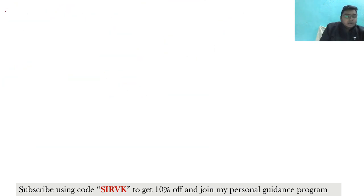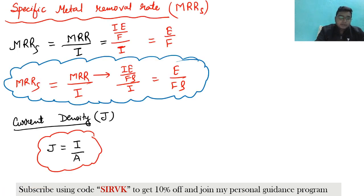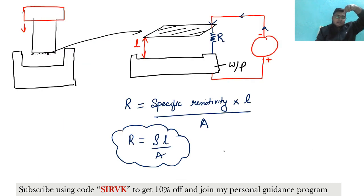So let me write it here: electrode feed rate. What is this electrode feed rate, my dear friend? Now see here, you can understand what the MRR is, EI by F rho. What is the unit? mm cube per second. Now what is the electrode feed rate? You are giving some kind of feed in mm in some seconds or some time, that is the electrode feed rate. Meaning you are doing some axial or vertical displacement per particular time, that is the feed rate.